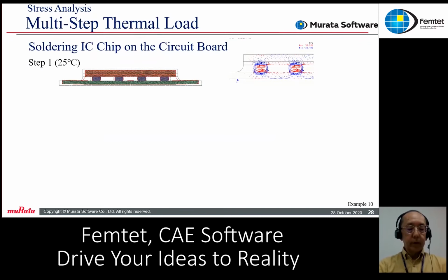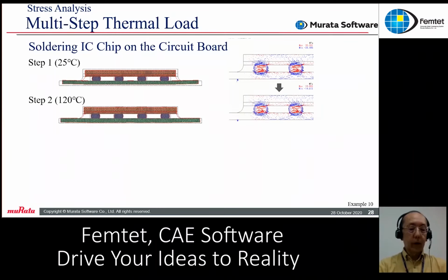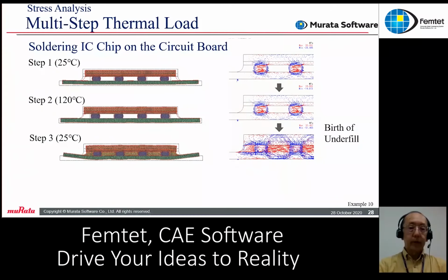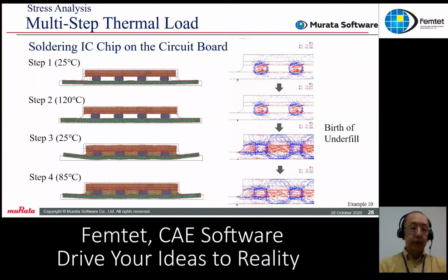Here, you can see the simulation results of internal stress distribution and the deformation on the right side. Results of step 2. And from step 2 to step 3, we are seeing the birth of the underfill. And at step 4, the IC is activated and the temperature goes up to 85 degrees.